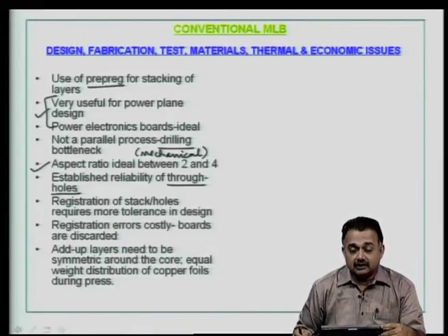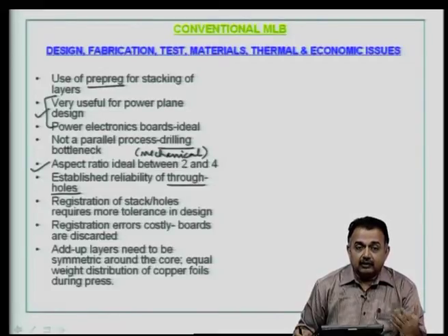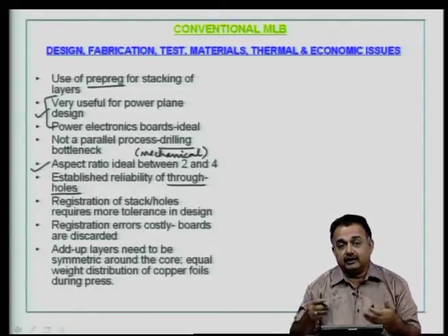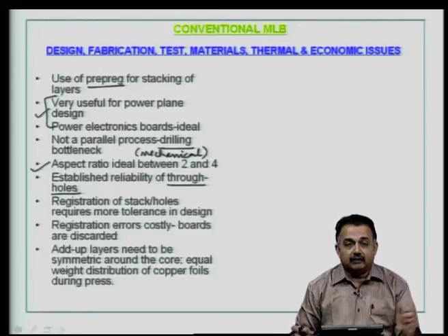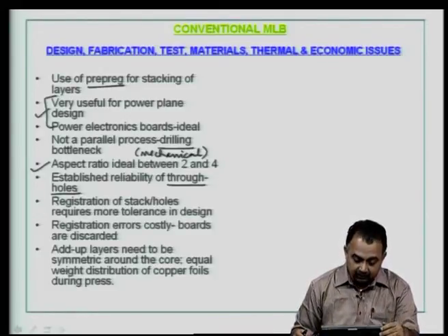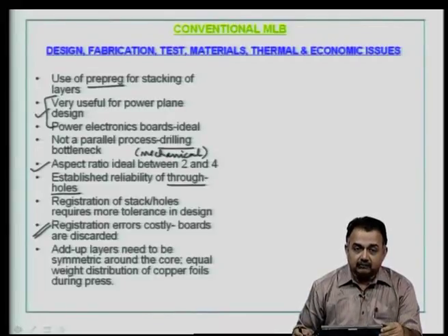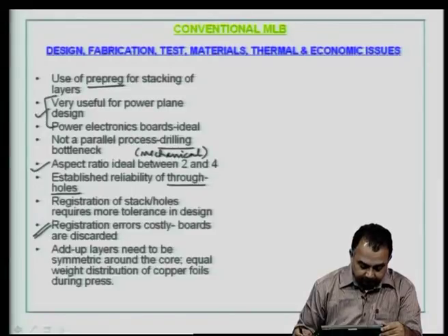So, make sure as a designer you understand in a multilayer board design what kind of tolerances you have given, especially if you are drilling, for example, layer 1 to 8, and if you finally see one of the inner layers is not connected at all. So, this to me is very important both from the design point of view and manufacturing point of view.